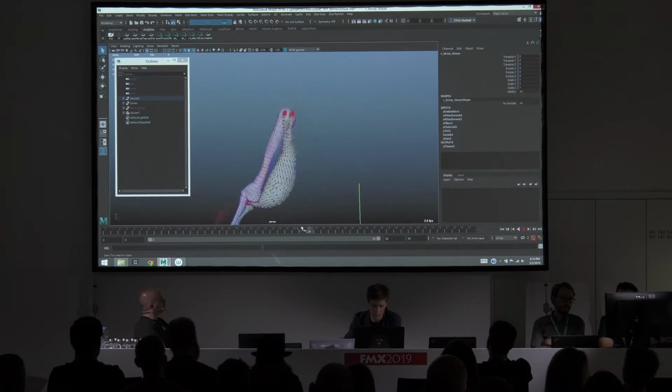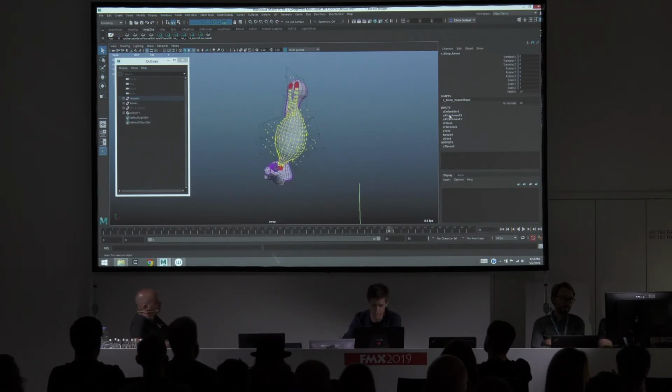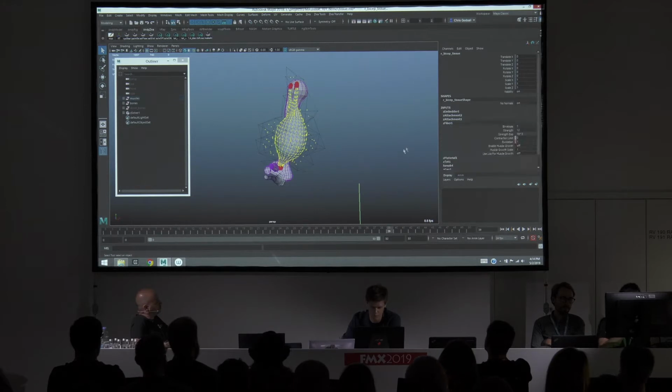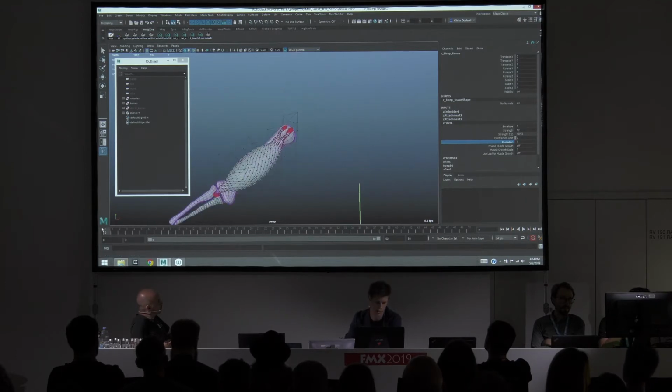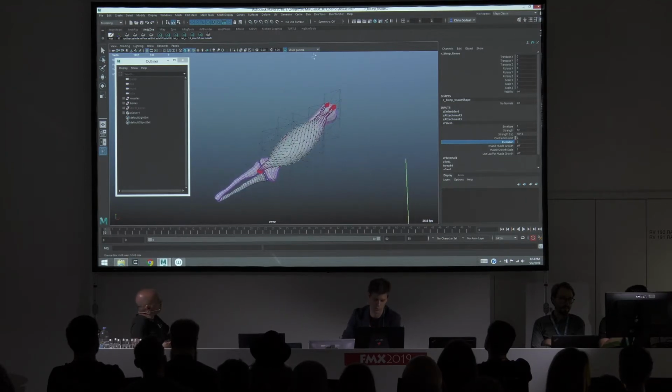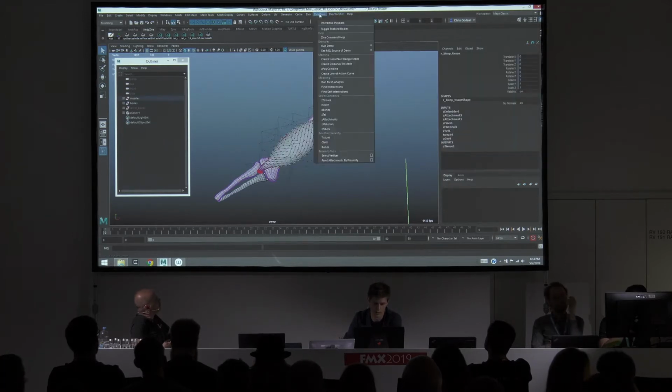So while that is cool to be able to keyframe this stuff, it's probably going to be quite tedious or laborious to hand key every time the bicep contracts, right? So we can actually delete that keyframe, and I'm going to choose to fire or excite the muscle with something called line of action, which is just a 2-point NURBS curve. So with this selected, I can use one of the Ziva tools to just help us make that curve.